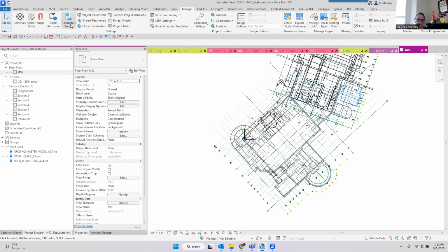What parameter services does is it allows you to host your shared parameters, if we're going to call them that, up on the cloud. And then everybody or people you give rights to can start accessing those shared parameters. What's really, really nice, and Jason says he's not completely sold on it yet, is that you can have a shared parameter master file, if you want to call it that.